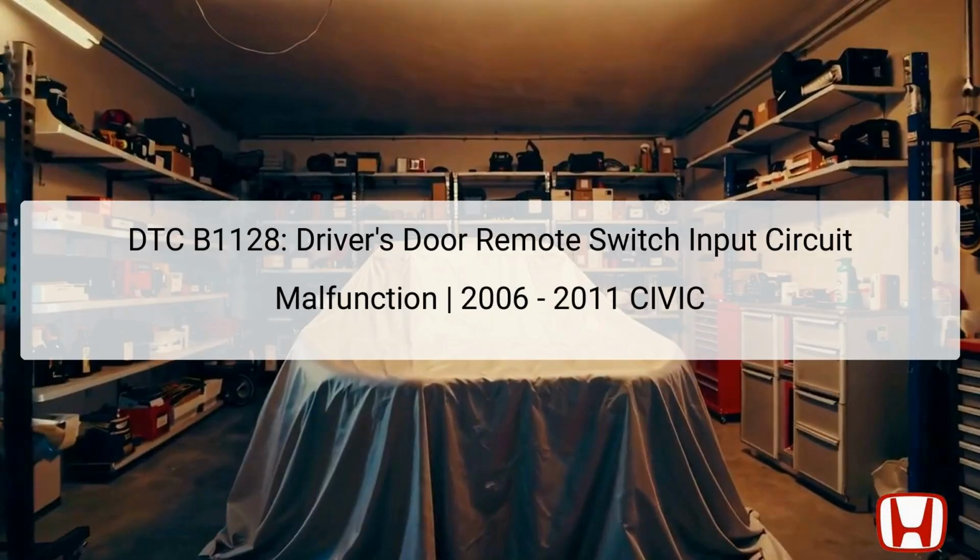The Diagnostic Trouble Code, DTC B1128, refers to a malfunction in the driver's door remote switch input circuit, specifically indicating a simultaneous input of lock and unlock signals. This DTC is prevalent in the 2006 to 2011 Honda Civic.